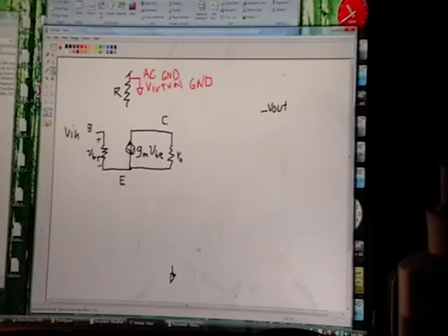And remember, the resistor was connected to the collector, so you connect the resistor to the collector. The emitter was tied to ground. So this goes here. This is connected to ground. V in went to the base, so that's good. And then V out was connected to the collector. And that's your new picture right there.